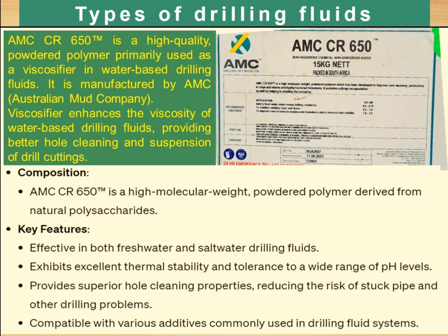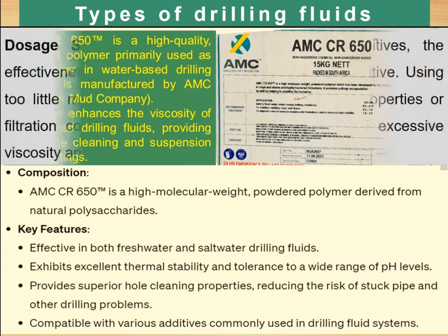What about the key features? Effective in both freshwater and saltwater drilling fluids. This particular AMC CR650 exhibits excellent thermal stability and tolerance to a wide range of pH levels, and provides superior hole cleaning properties, reducing the risk of stuck pipe and other drilling problems. Yes, there is a problem. It of course reduces the risk of stuck pipe, but if we are not utilizing it according to the prescribed dose, it can also give the opposite scenario. It is compatible with various additives commonly used in drilling fluid systems.